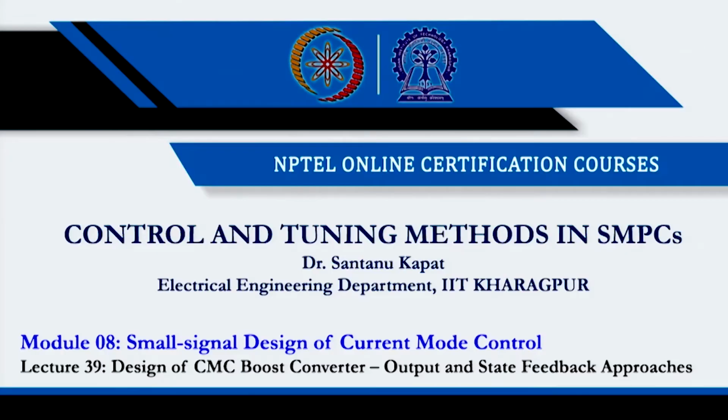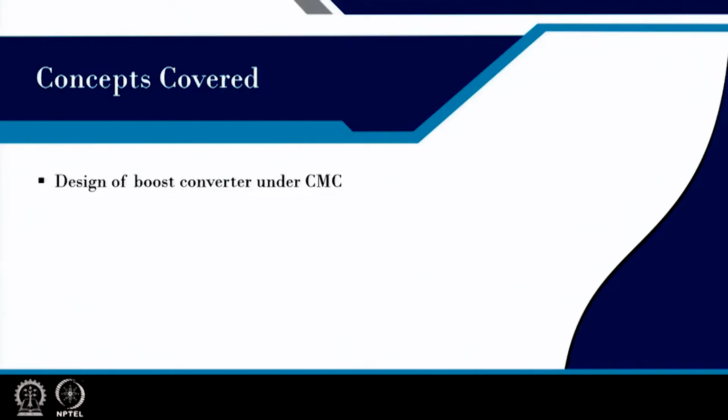In this lecture, we are going to talk about design of current mode control boost converter. Here, we are going to consider the traditional output feedback approach for design of current mode control. Then we want to consider an alternative approach, the state feedback design approach, but under current mode control. So, first we will design a boost converter under current mode control.